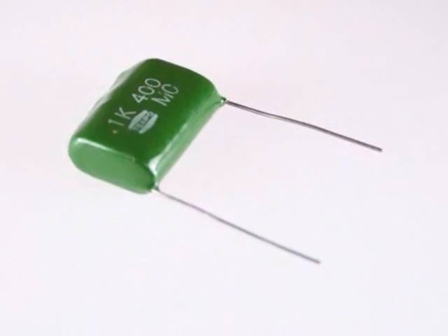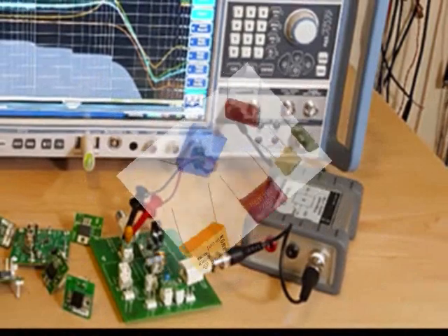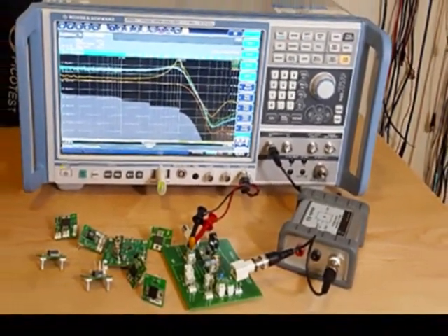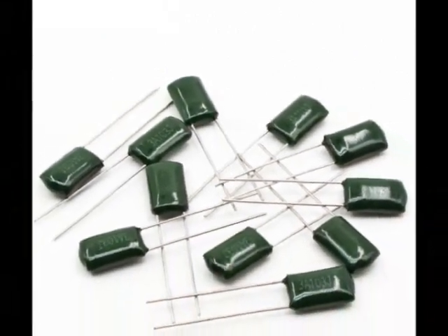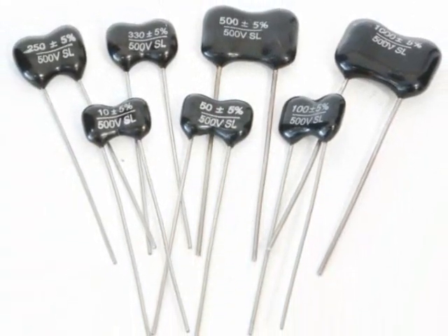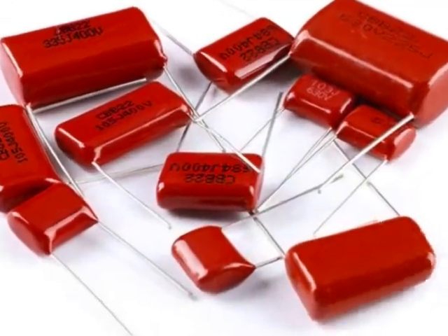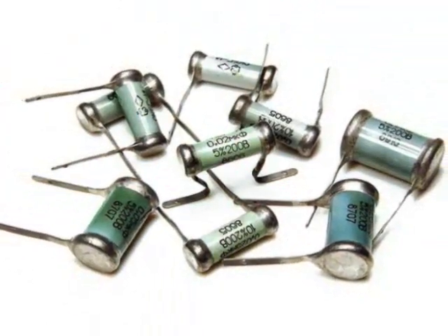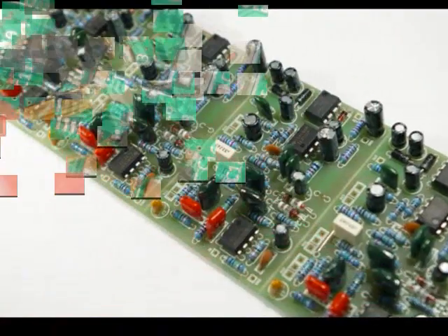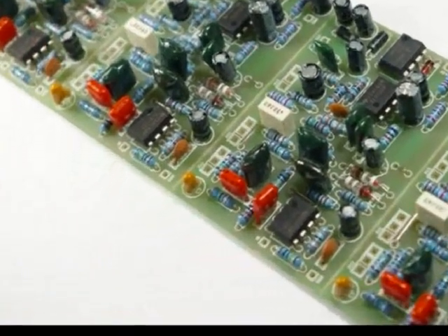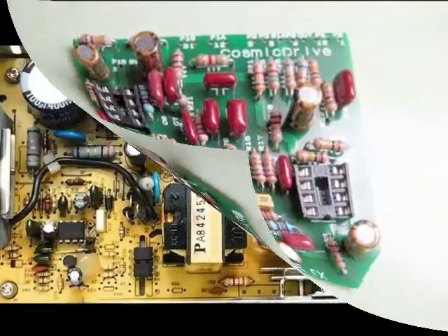But unlike electrolytic capacitors, they do not have positive and negative poles, and their capacity depends on the ambient temperature. This dependence on ambient temperature can be considered the biggest disadvantage of this type of capacitor. One of the important applications of ceramic capacitors is to eliminate noise in the power supply of circuits. Due to the excessive sensitivity of digital circuits to power supply voltage fluctuations, this type of capacitor is placed at the closest point to the IC in order to improve the power supply.